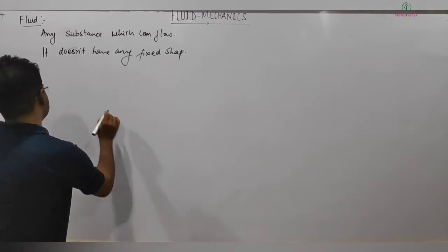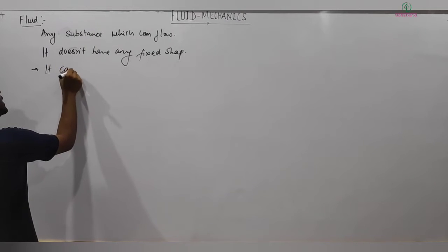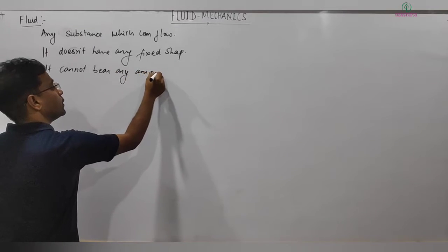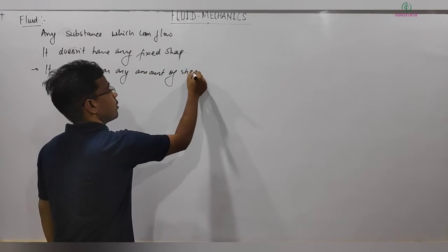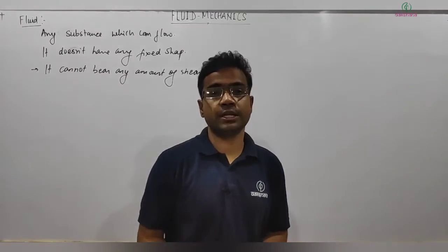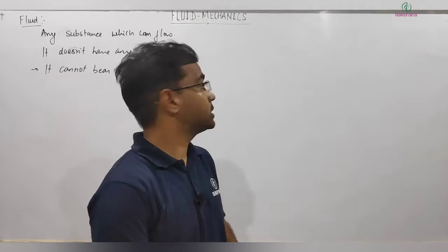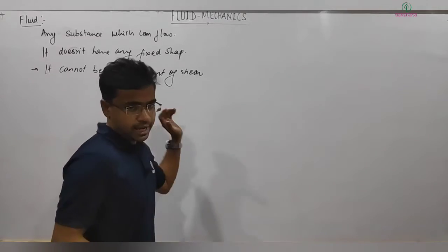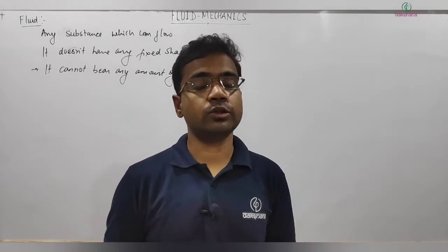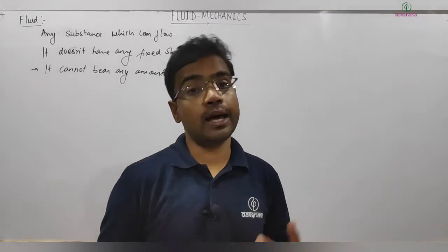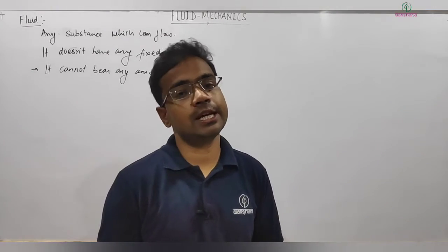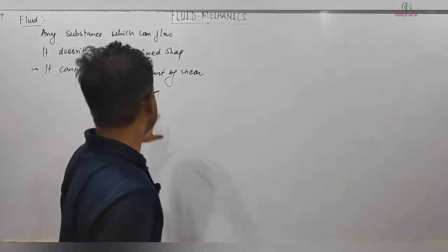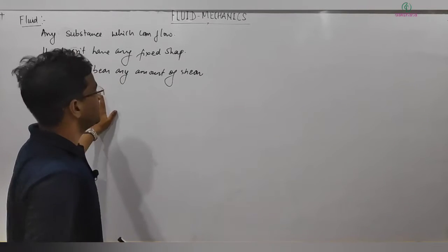And one more thing about it, that it cannot bear any amount of shear stress. If you are not aware of the shear stress term, you will learn about shear stress in the elasticity chapter. So fluid has the property that it can't bear any amount of shear stress, but yes, it can bear a large amount of normal stress. Normal stress, longitudinal stress, fluids can bear, but shear stress they cannot bear at all. That is one of the properties. So this is how we can define fluid.